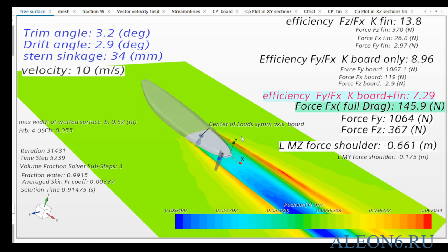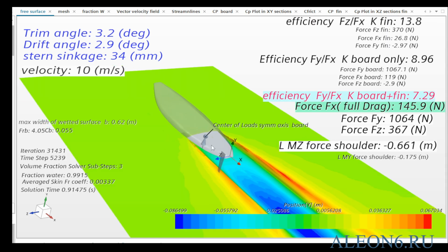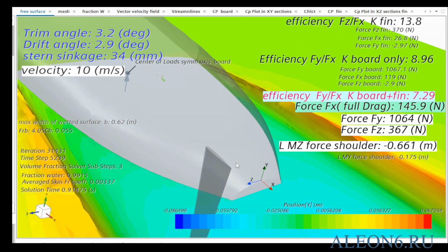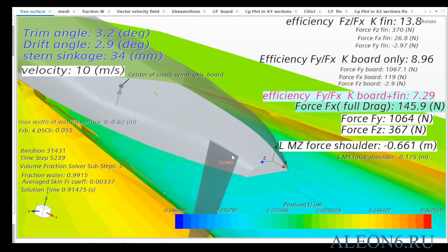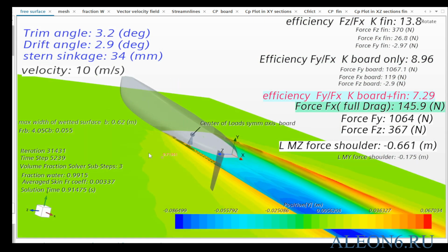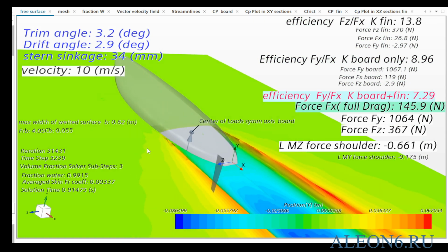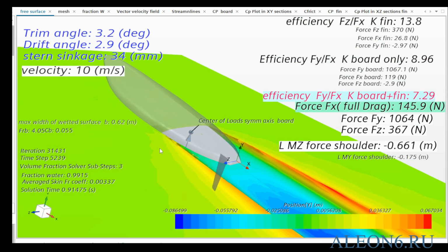We take a 42 centimeter fin, composed of a symmetrical NACA 9% profile, positioned absolutely vertically, meaning the board is not railed and has no heel angle. We also assume the fin to be completely rigid, meaning it will not deform under the influence of forces. There's no twist, no fin flex.